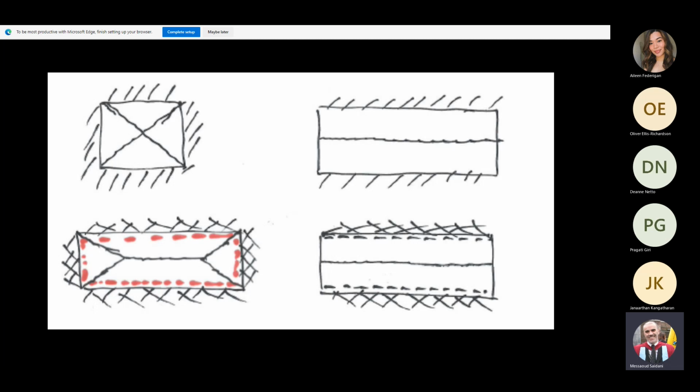That's exactly the same here. So for your slab here, you've got moments in the middle, where you have the maximum curvature. You've got a positive moment, sagging, and at the edges, because the slab is fixed at the edges here, there are what we call negative yield lines. So these yield lines here, dotted lines, refer to the negative yield lines to distinguish them from the positive yield lines. So the negative yield lines here correspond to the hugging moment. Is that clear? Yep.